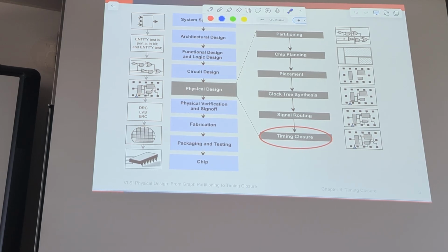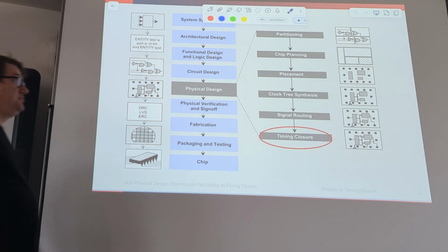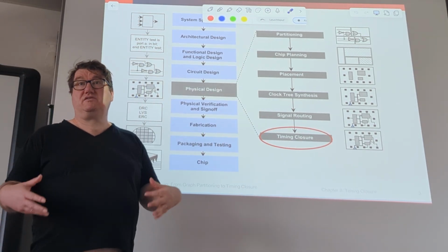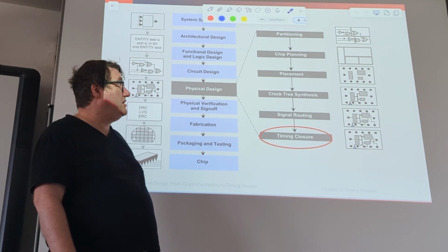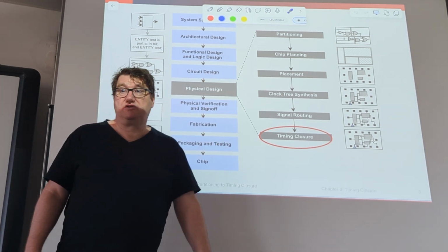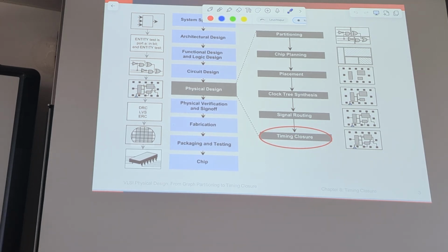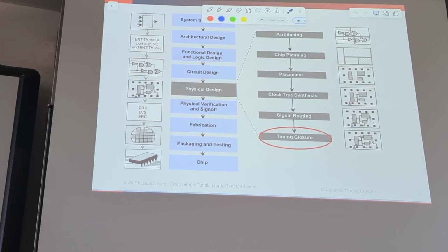Placing cells just by... so one other constraint for placement would be that it is actually routable. So how do you place it so that your wire length is not becoming too long, and it should not be too much area, of course. So other constraints: area, routability, but in the end you must achieve timing closure. That's what you normally work on. That's a hard thing.